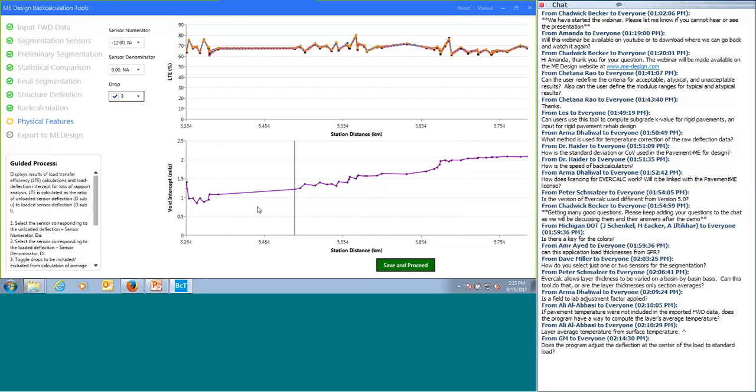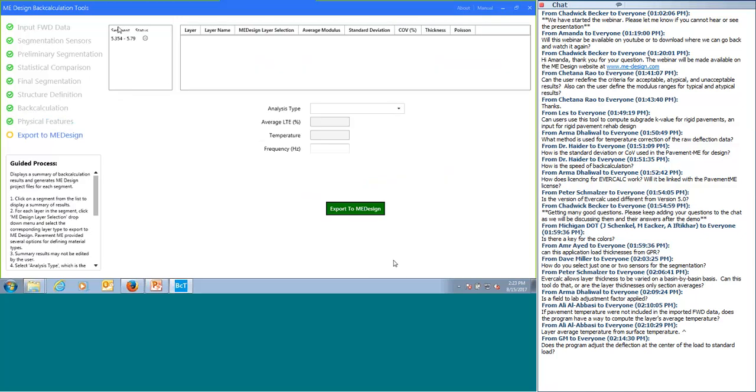So this is something where the theoretical void interpretation coincided with what the cores showed and led the department to realize they better do something with the top inches of asphalt concrete, different from the lower part of the asphalt concrete. So that's just an explanation. I'm going to proceed.